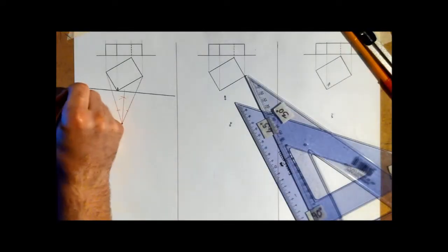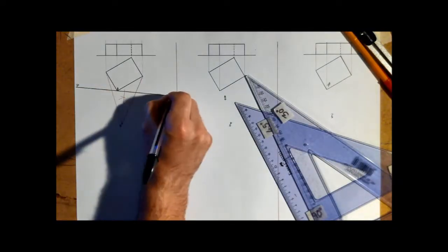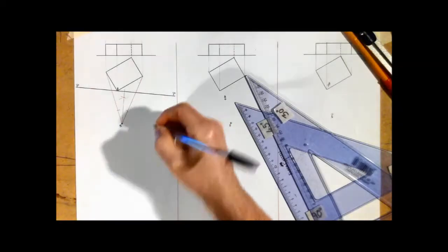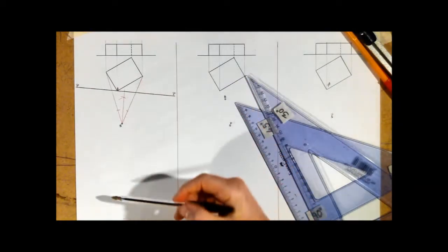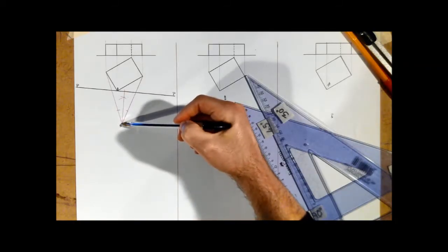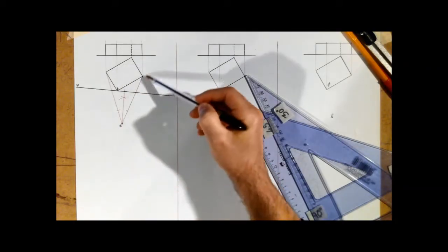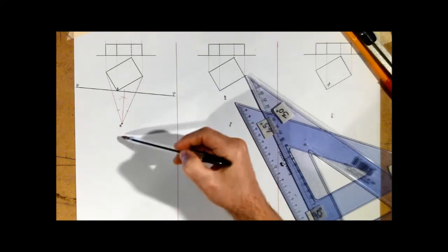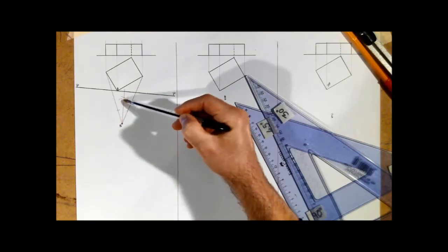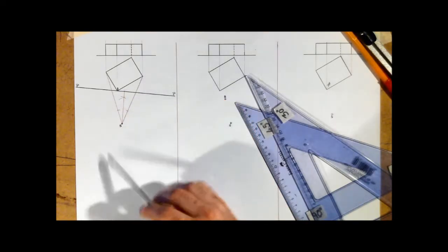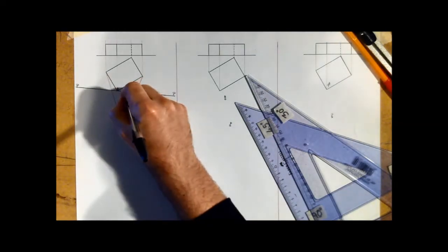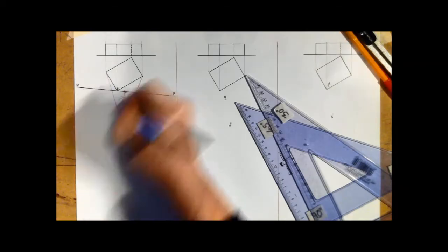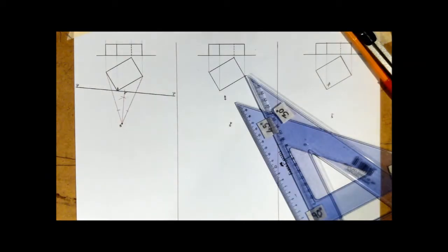Generally a picture plane will be indicated by two letters, PP, standing for picture plane, at either side of it. Very simple. There were only a couple of steps there: from the spectator, the extreme point on the left to the extreme point on the right, setting up our cone of vision and bisecting the cone of vision to get the line of sight. And with the line of sight, I'll put in a little symbol there for perpendicular. Perpendicular to that line of sight, we set up the picture plane through the corner A.